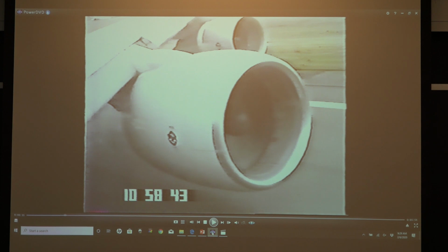It's a surge condition on takeoff. And this was actually, from my recollection, I believe a demo engine. And they purposely left out a couple blades. So what you're going to see when the video starts is there's going to be some vibration. The engine's going to rock back and forth, and then you're going to see uncontained loss out the back of the engine. Brian, what does surge mean? Surge is when the engine actually thrusts back.